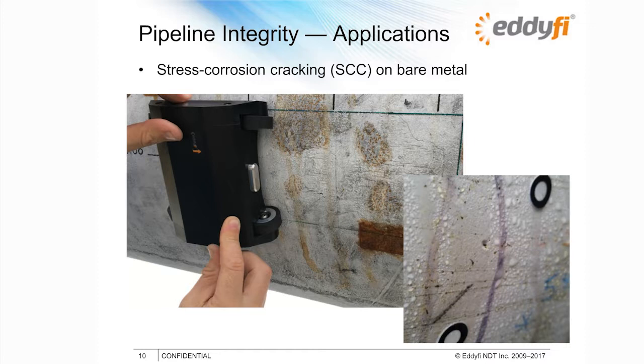For example, here we are showing you some imaging showing condensation on the surface of a gas pipeline, which is maintained at a low temperature, which makes the magnetic particle testing very complicated, if not impossible. With the TECA and the Sharck high-resolution probe, detecting SCC in those conditions in one single pass is not a problem. You don't have to prepare anything, and the result is shorter excavation, inspection, and repair time, and hence lower costs. We conducted some on-site inspection with some of our customers.